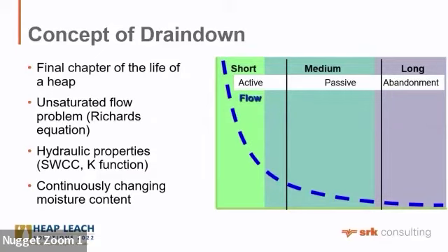So to talk about the concepts of drain down. We define drain down for the purposes of this discussion as the very final chapter of the life of a heap leach operation, of the heap itself. As the figure indicates, we have a flow that comes at us fast and furious in the beginning. It drops off relatively quickly, but then it takes a long time to get to some level that can be managed by passive water management solutions.